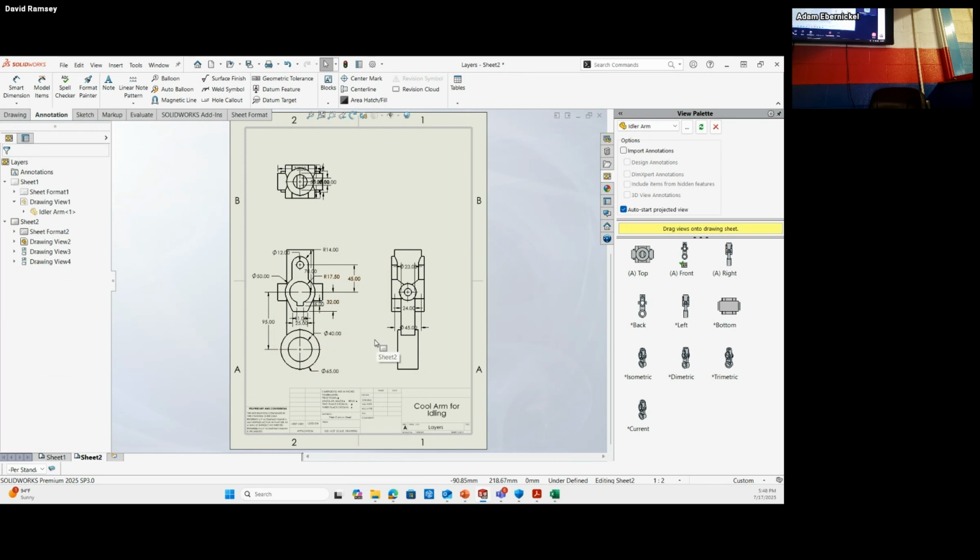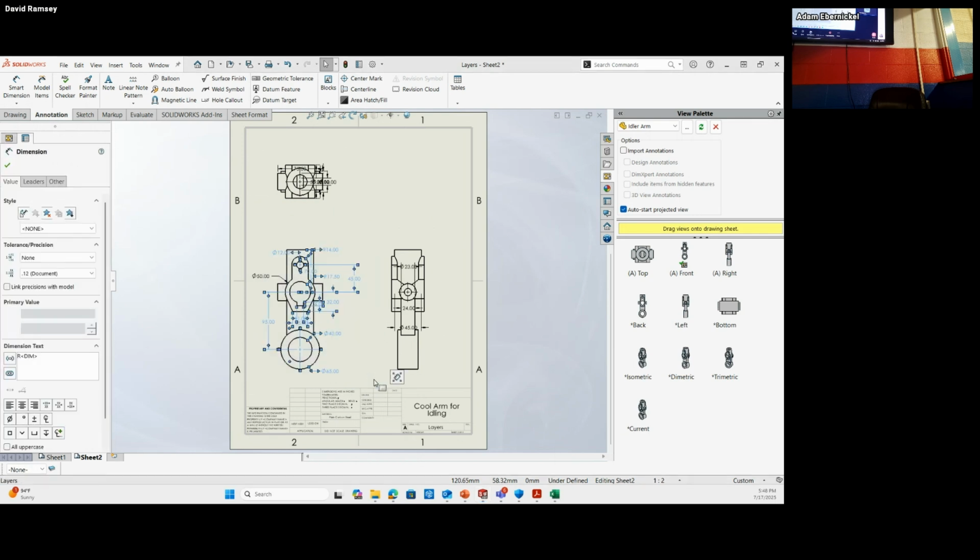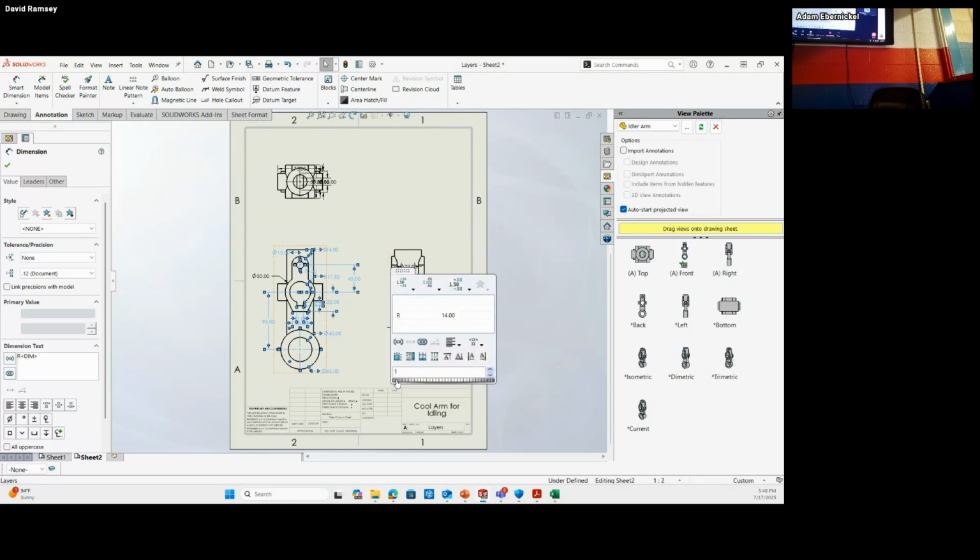So with that turned on, what I find that I've done a lot of times in order to clean it up, since SOLIDWORKS has what's known as an auto arrange, we can window select all the dimensions, and you get what's known as the dimension palette. That's this little pop-up icon that pops up here. And truth be told, this is a very, very powerful tool. Most of what you can do in the PropertyManager on the left right now, you can do right from this tab, right? We can do tolerance, precision, add reference dimensions, add inspection labels, all sorts of good stuff, right?